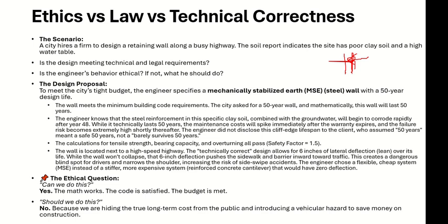It is made up of concrete. Concrete is heavy, and it has steel in it, which is also heavy. But the problem is the site conditions on this site. They have clay in it, and they have a high water table. Okay, so there are two problems with the site there: high water table, and the soil is weak, naturally weak. Clay is a weak soil.